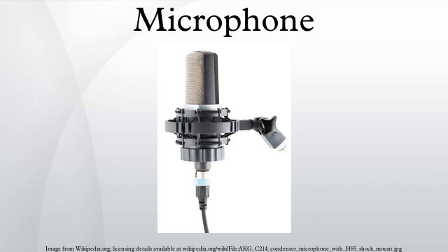The changing pressure deforms the granules, causing the contact area between each pair of adjacent granules to change, and this causes the electrical resistance of the mass of granules to change. The changes in resistance cause a corresponding change in the current flowing through the microphone, producing the electrical signal. Carbon microphones were once commonly used in telephones. They have extremely low-quality sound reproduction and a very limited frequency response range, but are very robust devices.